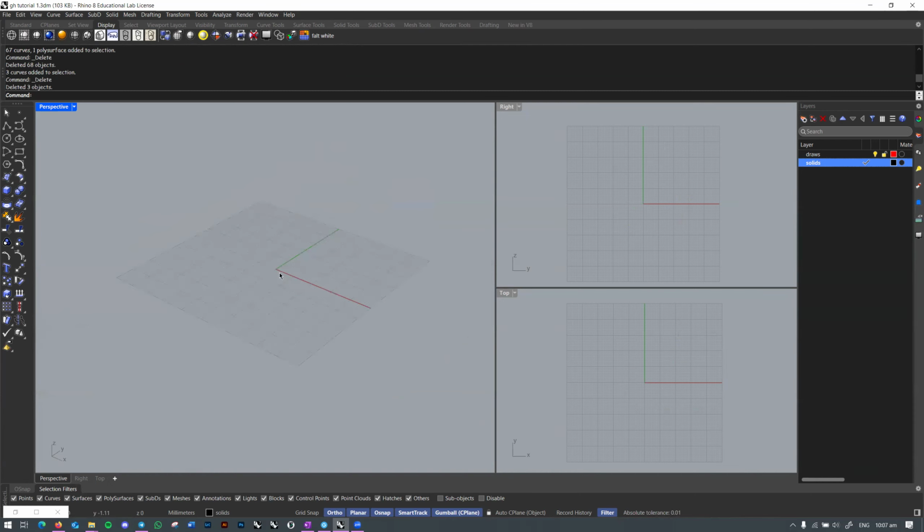And today I'll show you the basics of Grasshopper and how to do things that you would do in Rhino in Grasshopper as well. Whatever you can do in Grasshopper, you can do in Rhino. It's just more tedious. Usually Grasshopper helps when you have many of the same commands to run, so you don't type union and then Boolean union all the time. You can automate the process. Or you can use Grasshopper as a computational form finding tool. So those are the two benefits it can give you.